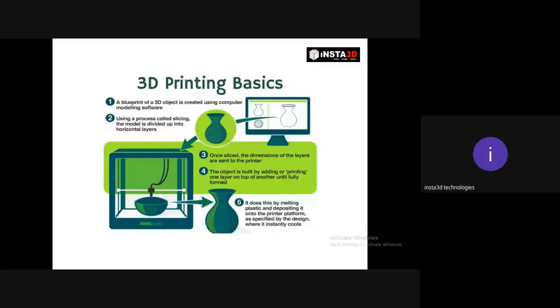And by using a slicer, this model is sliced into thousands of horizontal layers, and these sliced layers are transferred to a 3D printer, and the 3D printer operates on that. How is it doing? If you number the sliced layers 1, 2, 3, 4, 5, 6, each number will be processed in that same order, 1, 2, 3, 4. And this first slice of layer will have its own G code and M code.